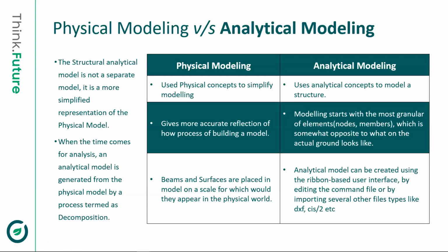At the time of the analysis or loading, you have to decompose your physical model to the analytical model, and in that you can assign loads and then do the design. Because the physical model is a bit complicated in terms of analysis and design, for the simplest form, you just have to click on the decomposition option and you will enter the analytical modeling. If I may, let me just show you. Just give me a moment.